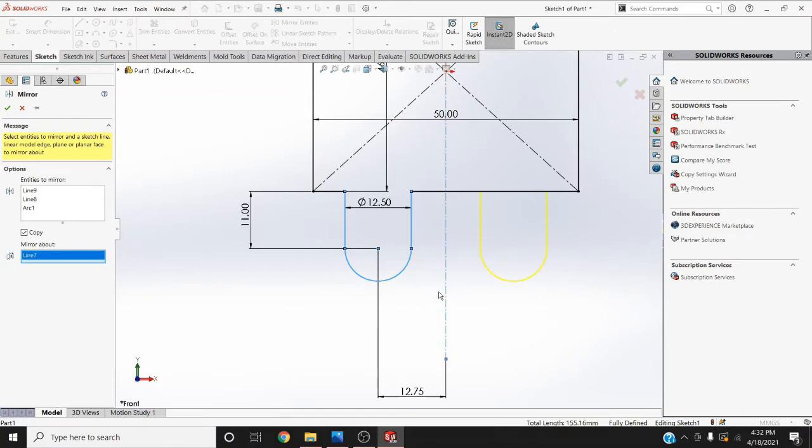Once I select this line, as you can see, there is a preview over here, and it's in the right place. Yellow means it's preview. Now we are ready, and we say okay, this is fine. Now we hit the green check mark, which is at the top left hand corner, over here. I click on it.